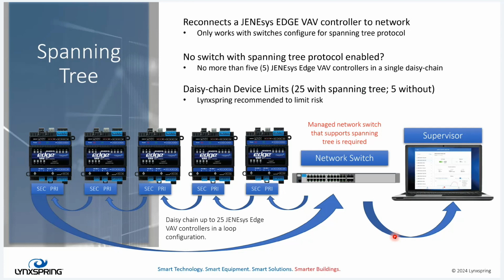Okay, this is an interesting one, but one thing to note, you'll see the primary and secondary Cat5 connections on these VAV controllers that do allow you to daisy chain, and that is far and away the old method of home running them back to several switches.